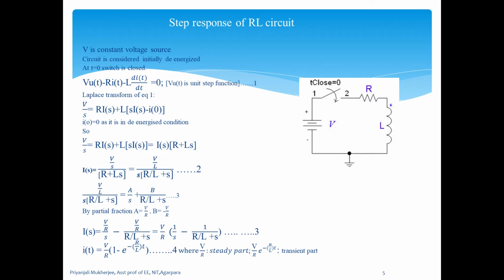Now, when the current is constant, then the voltage across the inductor is 0, because under steady state DC the inductor acts as a short circuit, and AC is constantly changing, and hence the inductor will create an opposition of voltage polarity that tends to limit the changing current.